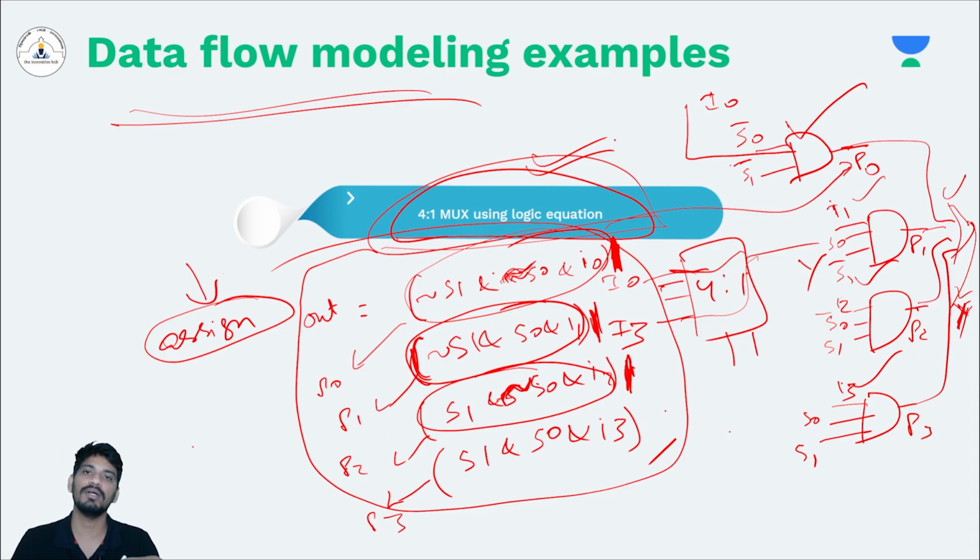In gate level modeling, we have to use gate level primitives like NOT gate, AND gate and OR gate to define the circuit, but here we are using simple operators like the negation operator, AND operator and OR operator to build the 4:1 multiplexer. We will design this in the live coding session, apply different stimuli to it, and check the functionality.